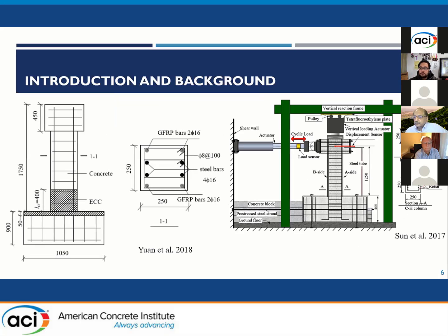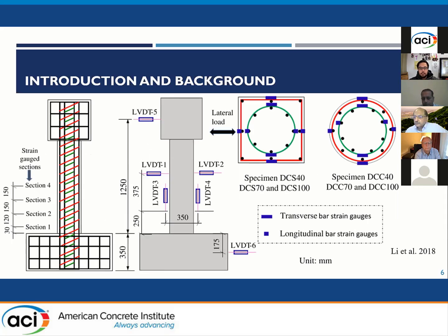I am talking about something like this, where we have steel and GFRP together in the section, as longitudinal reinforcement and as transverse reinforcement. This layout does not serve the purpose much because both are in the same layer, so they have the same level of exposure. But it could still be used for other purposes. Maybe something like this, where we have the steel placed at the inner layer and the GFRP placed at the outer layer.